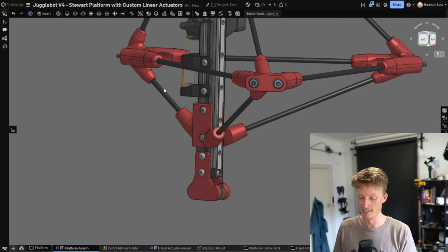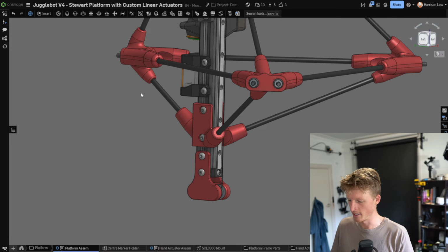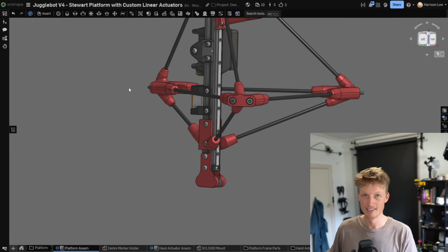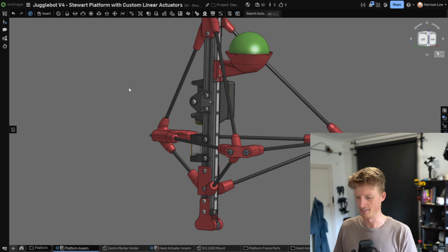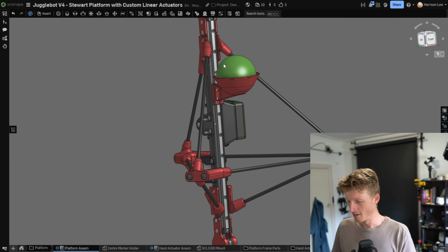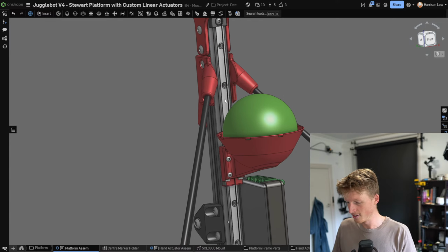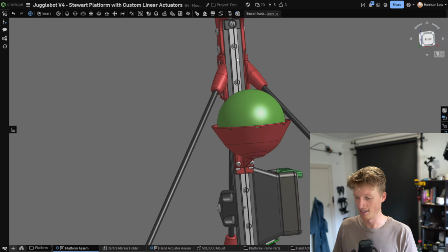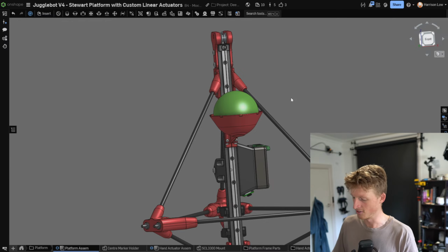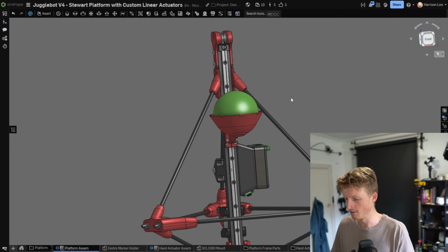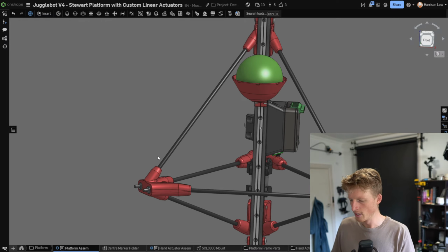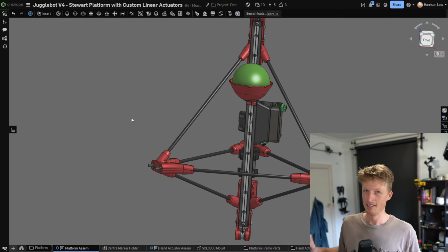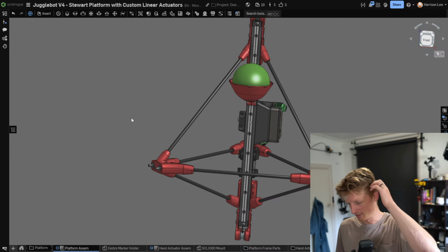The 2020 extrusion is definitely not the length that it's supposed to be, because I cut that by hand with a hacksaw. So that's not less than 0.5 millimeter correct. The only thing that I do know for sure, I guess, is the length of the linear rail. But even then, the position of that linear rail on the 2020 extrusion is probably not spot on. When I was making this frame, that was pretty damn stressful, I've got to say.